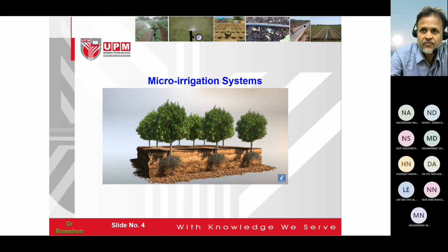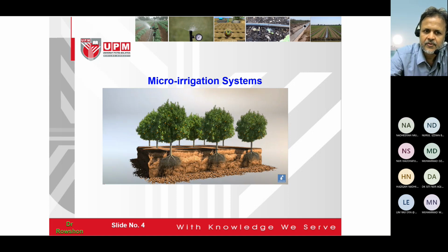This information you will find from the emitter. When we buy the emitters, the manufacturers will give this information. Otherwise, maybe you can buy and then test in the field. Let's say you operate for 1 hour. After 1 hour, what is the weighted diameter? So you can find it. This is called DW. So DW will be given.